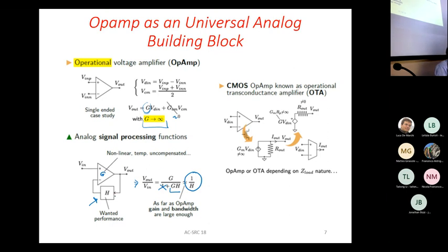A passive circuit means that H is typically less than 1, so it is an attenuating function. But when you put a function less than 1 in the denominator, clearly you are still achieving gain. So you control the gain with this passive function, and you use an op-amp just to set, thanks to the stability and precision induced by the feedback, a very precise gain.